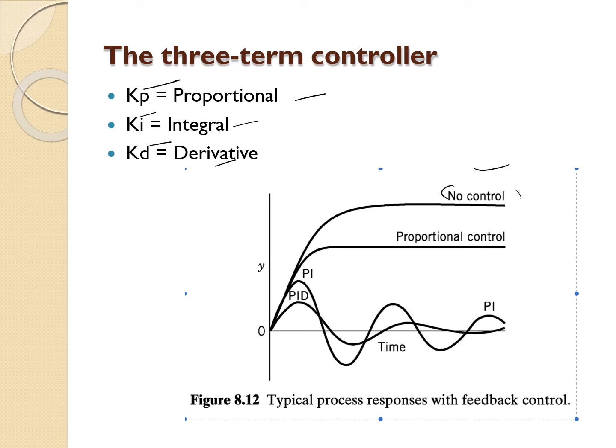Okay, normally the proportional control will not successfully bring the control variable to its set point. There is some steady state error. So it can bring it near to the set point, but not exactly on the set point. That's why we have to install the PI, and that PI will eliminate the steady state error and push the control variable to its set point.